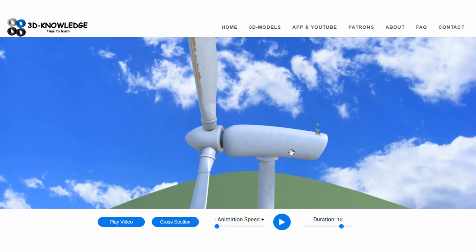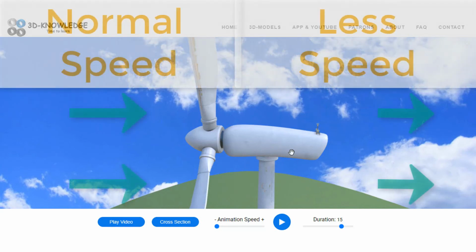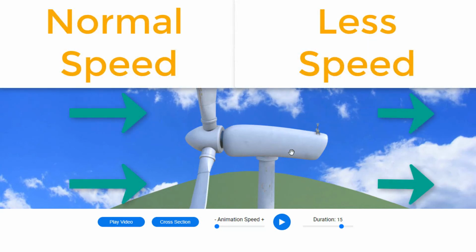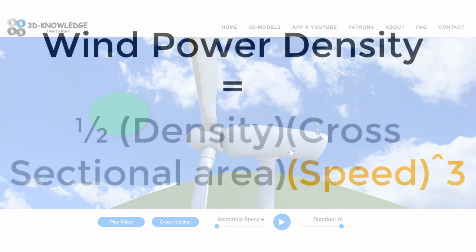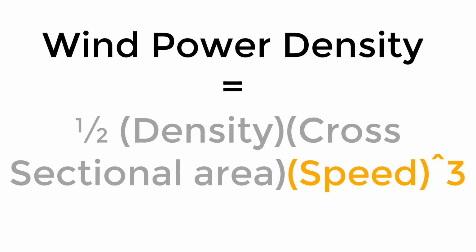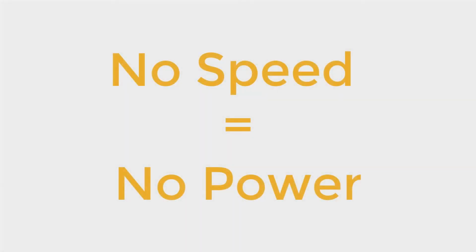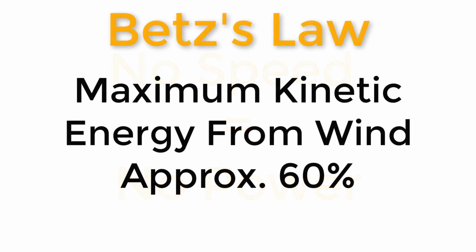onto the blades. And this causes almost like a traffic jam type of problem. The wind to the left side of the screen can no longer pass across the blades as quickly as the predecessor did towards the right side of the screen. So we don't want this. Obviously, we still want the wind to keep flowing. We don't want to impair it or slow it down significantly that we can no longer extract any more wind. Okay, that's slightly over exaggerated there. You're always going to be able to extract some wind. You're not going to stop it completely. But my point is, you can only ever get to a rating of 59.3% efficiency because of this problem. Now, this efficiency rating of 59.3% is well documented and it's referred to as Betz's Law.